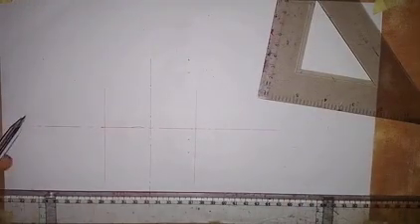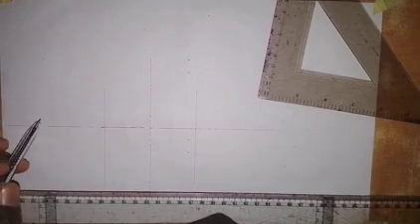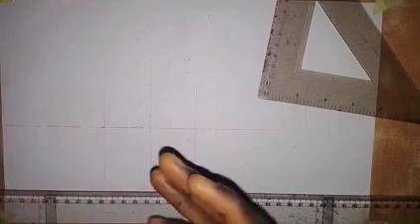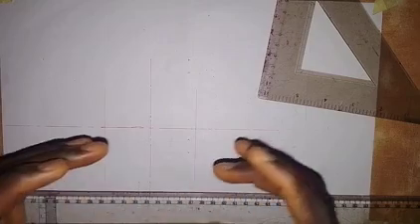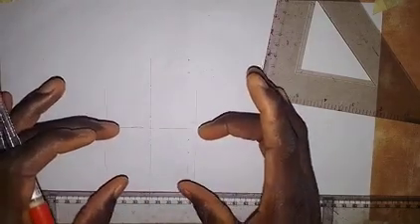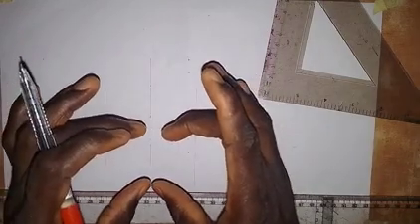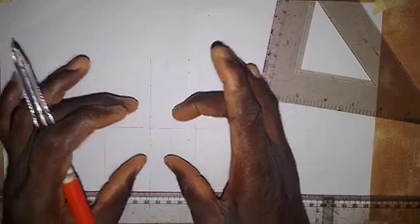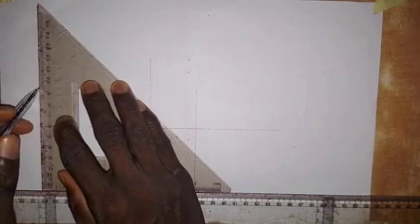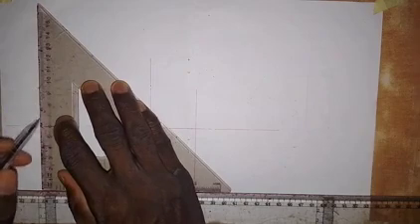For the 40 millimeters we have taken to both sides, the next thing is to construct a hexagon on this side. I'm not going to make it a whole hexagon, I'm just going to draw half of the hexagon. You are going to see the way I do it. I want to use it to get the front elevation of that horizontal hexagonal prism drawn here. So I need to move away a little bit. This is okay. Then I'm going to draw a vertical center line here.